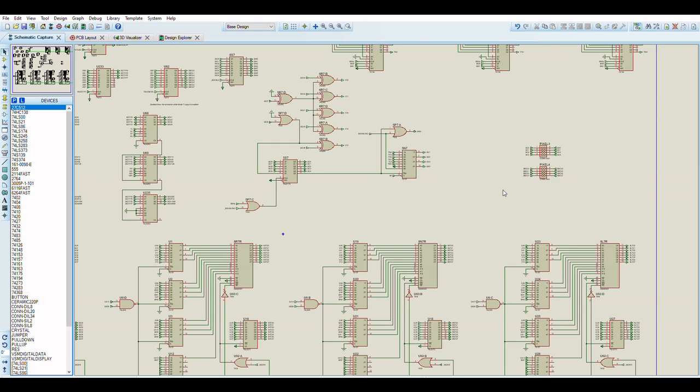If we had 2 sprite boards sandwiched together, that would give us double the number of sprites. If we had 2 tile layers sandwiched together, then we would have 2 independently scrolling tile layers using independent graphics, and that would also be quite cool. It'd be nice for parallax scrolling and stuff like that.